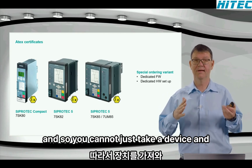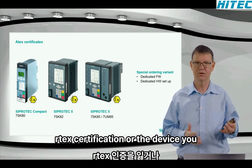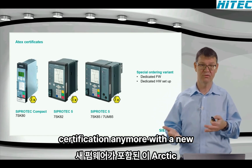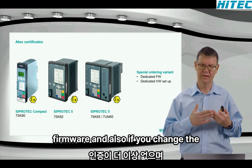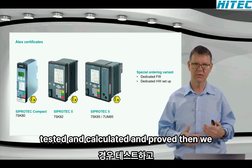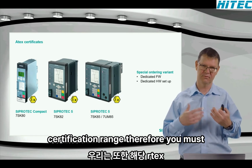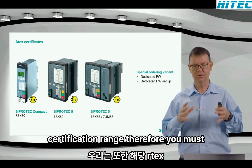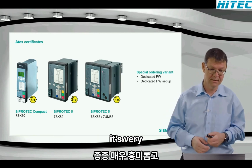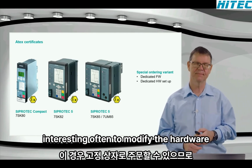And so you cannot just take a device and upgrade a firmware, then you lose the ATEX certification, or the device you have does not have this ATEX certification anymore with a new firmware. And also if you change the hardware setup, and it's a hardware setup we have not tested and calculated and proved, then you're also falling out of that ATEX certification range. Therefore, you must just take the device as you can order it as a fixed box in that case. Although it's very interesting often to modify the hardware.